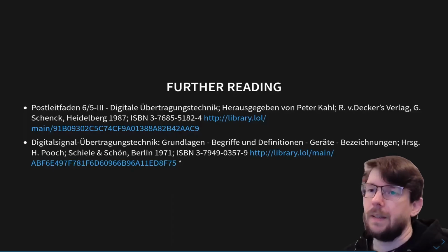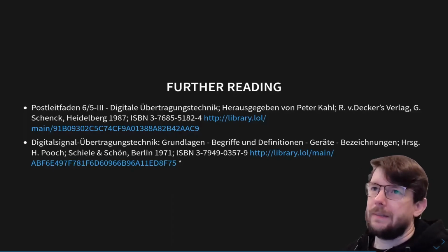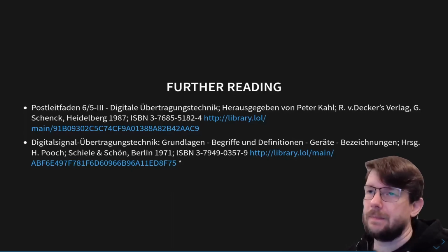push dummy data. The other option was just we can actually reserve some, like the buffer that we have for the E1 is gigantic. We don't use all of it. And we can easily just pre-fill an entire multiframe worth of FF at the initialization time. And then when you submit the descriptor of what you want to push to the E1, you just set the pointer to, okay, just read that dummy frame and push that and be done with it.